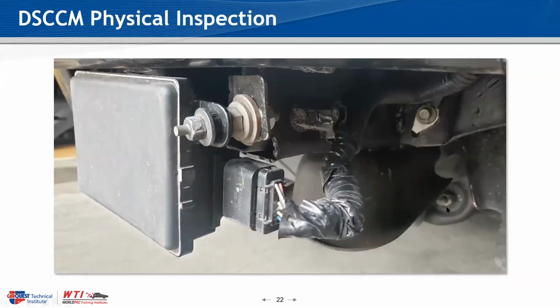Now, I don't know about you guys, but I've never seen this whole 2 nuts and a bolt pointing the wrong way and with a couple extra washers on it used in a factory setup. And this bracket that this bolts to looks probably not in new shape. And I apologize, I didn't get a better picture, but from underneath, you can kind of see it right here at the bottom of the bolt. This frame horn is bent, and then there's some welding over here that's been done. So if you look kind of closely, it's broke.